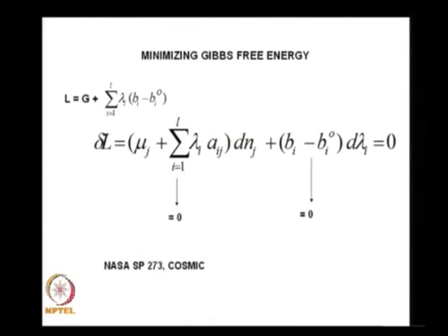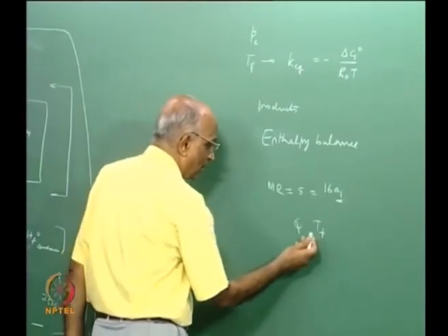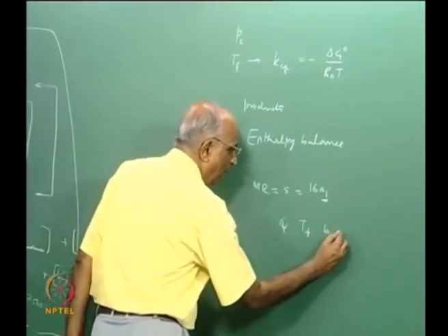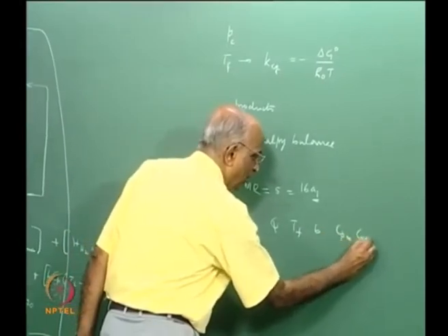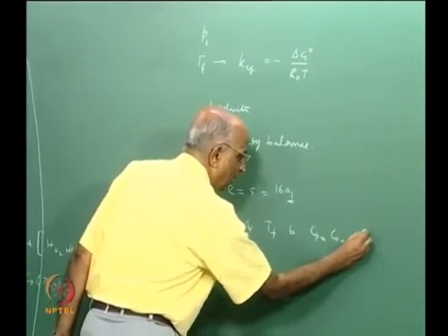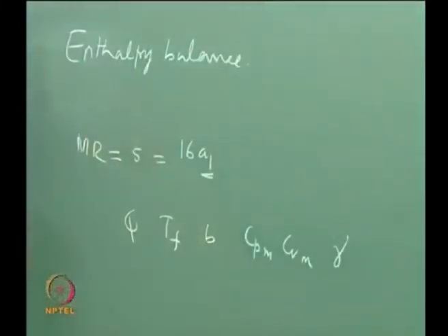This is how we determine the products of combustion. Once you know the heat of reaction and the Cf, and the distribution of B, I can find the Cp for the mixture, the CV for the mixture of the products, the gamma, and I can determine whatever performance I want to determine. Let's take a look at the results again.